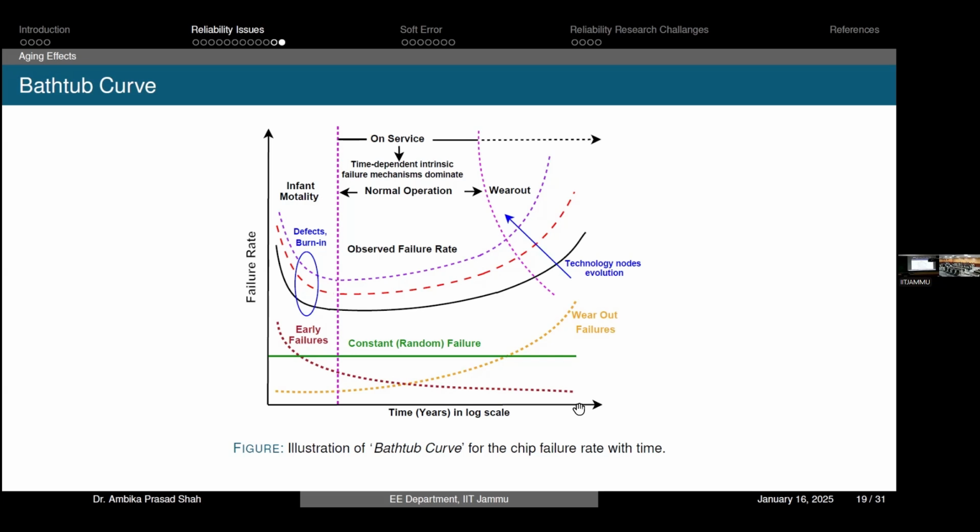Yes, so why do we need high K? See, if I'm using low K, to get the same dielectric constant the thickness will be less. High K helps us get the equivalent dielectric constant with more thickness. If you have more thickness, there is more scope to collect defects, and maybe TDDB will be less in high K as compared to low K, because the thickness is very small in low K. I'm talking about the same constant; if I say the same constant, it means your thickness will be different in both materials. So high K will be better in terms of TDDB.